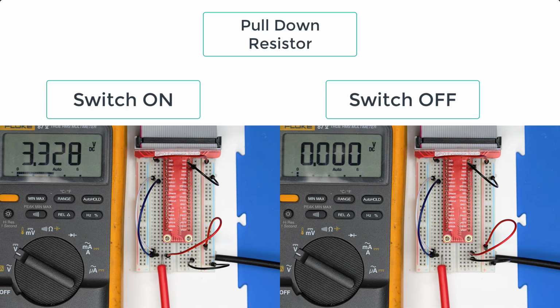Hopefully you took the opportunity to figure this out on your own. What you should have seen with the switch in the on position, or the positive jumper wire connected to pin 13, is that the voltage went to 3.3 volts. The opposite happens when the switch is in the off position, so without any positive connected to it, you should have seen a value of 0 volts. If you did not receive these values, talk to your instructor and see what went wrong.